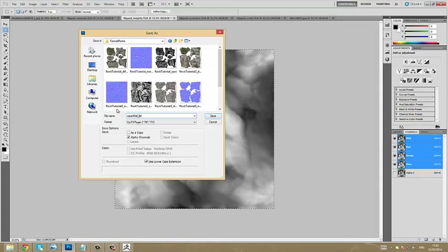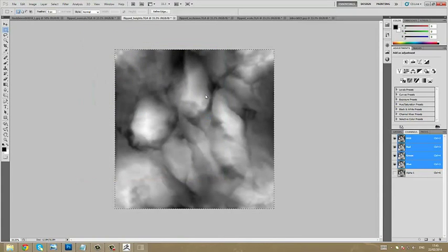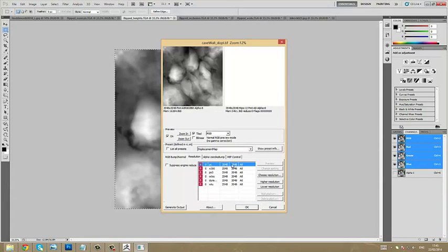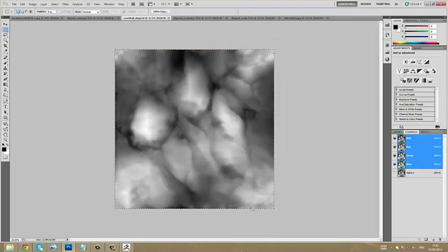Okay, so the proper naming convention for displacement maps is DISPL. For this map to be able to work properly inside CryEngine as parallax occlusion mapping or tessellation, doesn't matter, it has to have this postfix, DISPL, at the end of its name. Just click Save, and here just select displacement map from the list of options, choose PC, and just press OK.